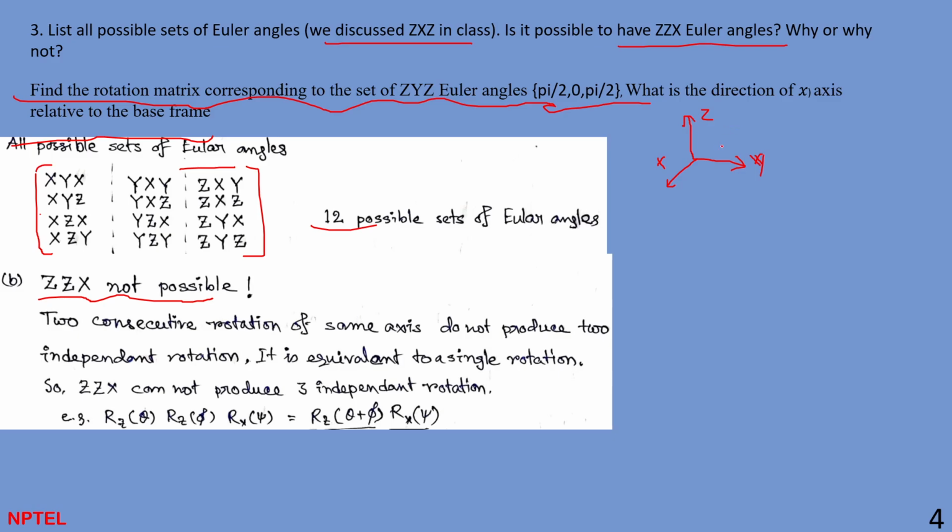When you do a transformation here, it is z, z, y. First we rotate along this, we do a rotation which is theta here, and then we again do a phi rotation here, because the Euler angle needs to be post-multiplied. It's not rotating with respect to the fixed frame.